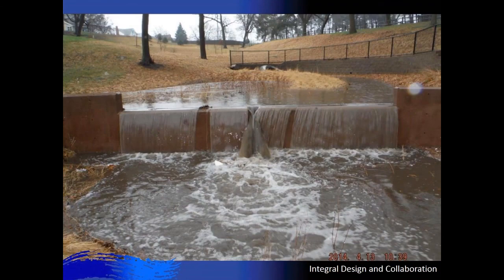So this is the one thing that I didn't mention: we integrated some bioretention cells in between those weir structures. In this photo, you can see the gangly vegetation up there that's kind of dead. This is in the winter. That's a bioretention cell where the water comes around that berm, the yellow berm there, and comes up to the wall and then backflows up into the bioretention cell. So it's offline, is what we would say, and then the main water flow goes over the weir structure. Yeah, so it's a great example of even having kind of multiple functions in the channel itself.